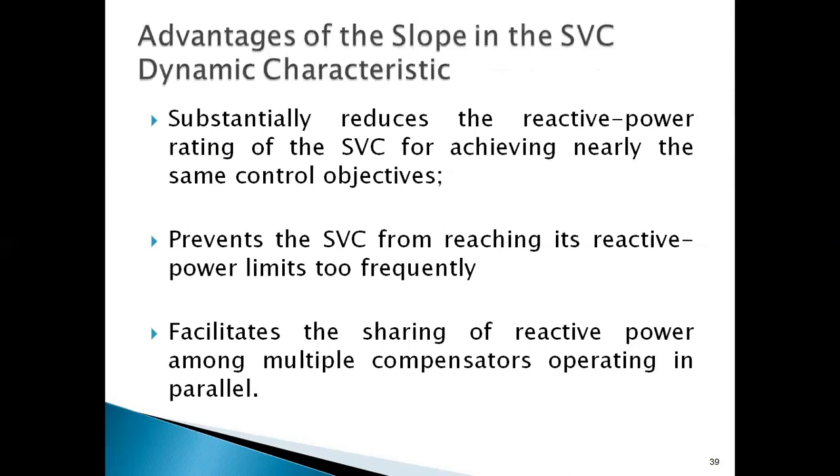And these are the advantages of having a slope in the SVC dynamic characteristics. One is that it reduces the reactive power rating of the SVC for achieving nearly the same control objective, and that we are having because of the overcurrent limit.